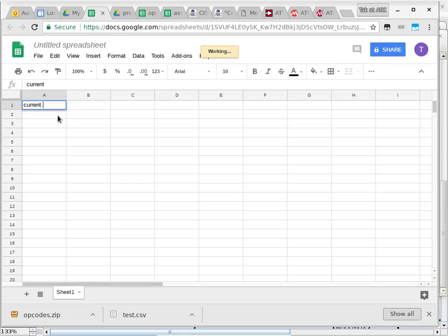So we say, okay, we have current draw, and it is 200 micro, right? So it's 200 E minus 6. Getting back to the floating point or scientific notation, right? Because it's 200 times 10 to the power of negative 6. So that's our current consumption. The voltage is 1.8 volts. We'll just say 1.8. And then over here we'll say battery capacity. So we are measuring everything in ampere. So this time we'll specify 3, but it is 3 amp hours.